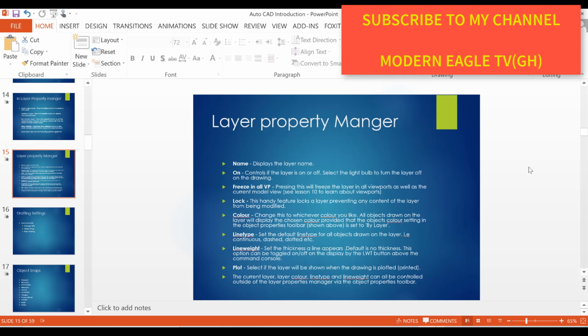Lock: this handy feature locks a layer, preventing any content of the layer from being modified. Color: change this to whichever color you like. All objects drawn on the layer will display the chosen color, provided that the object's color setting in the Object Properties toolbar shown above is set to ByLayer.